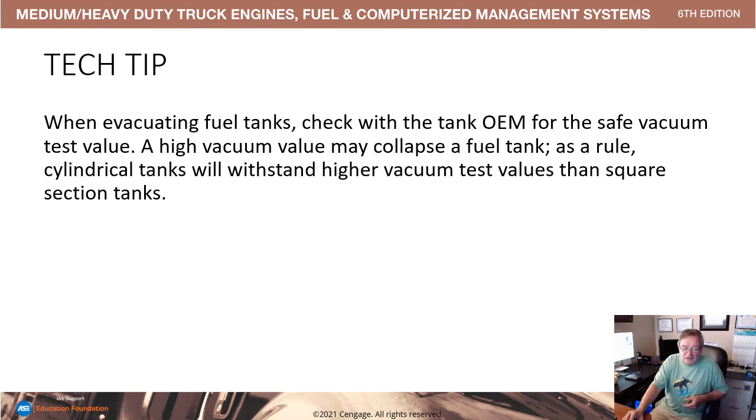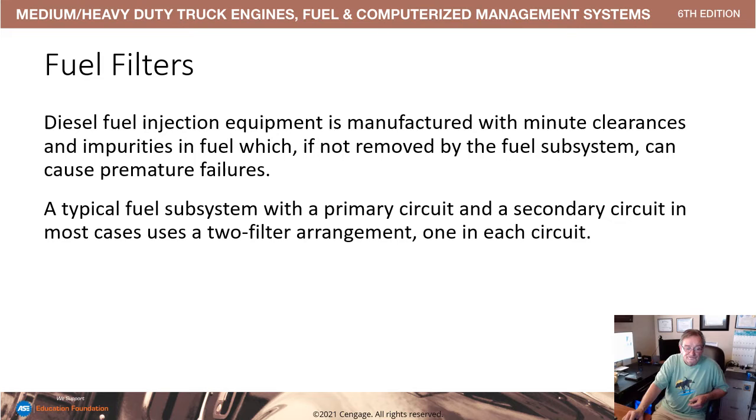When evacuating tanks, check with the OEM for safe vacuum test value. High vacuum value may collapse a fuel tank. As a rule, cylindrical tanks will withstand higher vacuum test values than any square section tanks.